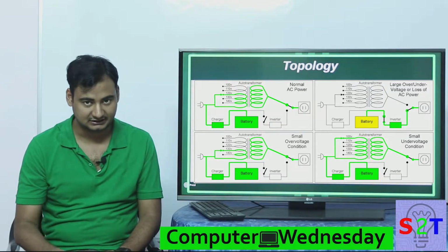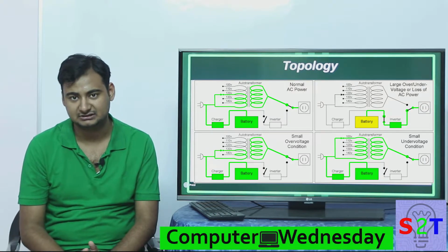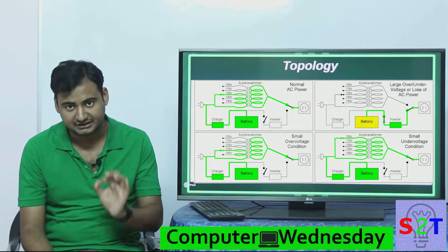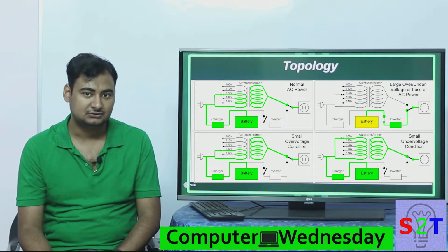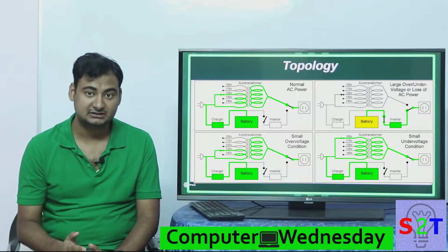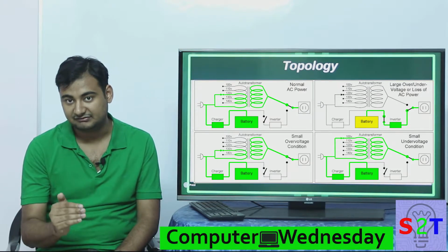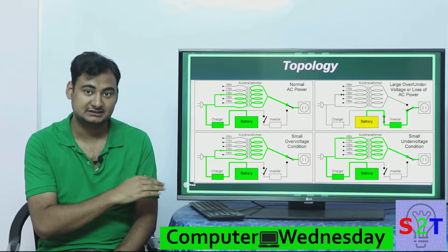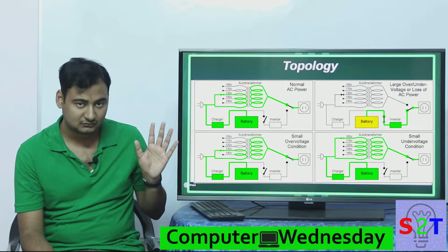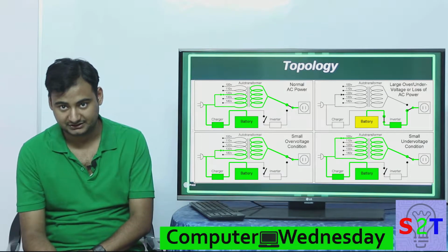There is a bit of switch delay, and earlier very old inverters used to switch in around 10 to 15 milliseconds. Now they switch as quickly as possible, so their target generally is below 5 milliseconds. Your computer's capacitor should be powerful enough to hold a charge for 5 milliseconds, and this will switch. Generally they switch under that, and as they get older they might take longer. So all you have to understand is there is an auto transformer inbuilt into your UPS.